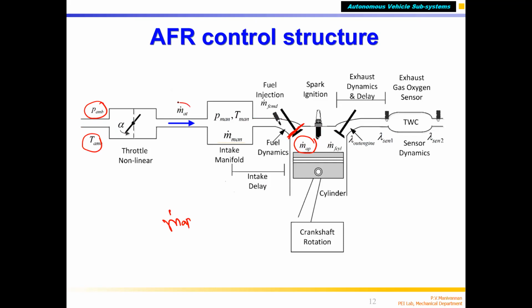So due to this, there is one mass flow rate entering past the throttle valve. This is the air mass flow rate, which in turn will finally build up, because the throttle body is also a chamber. It accumulates some amount of air, correct.